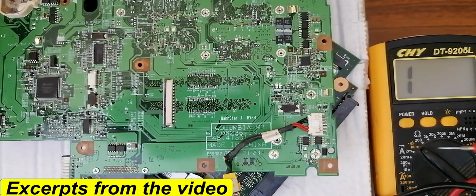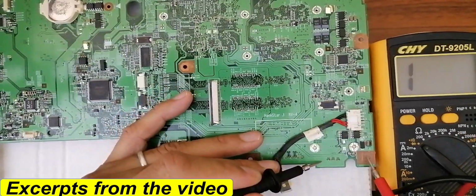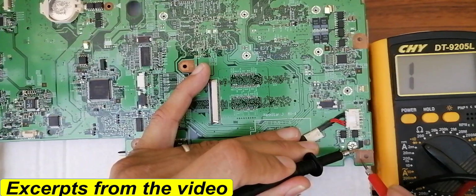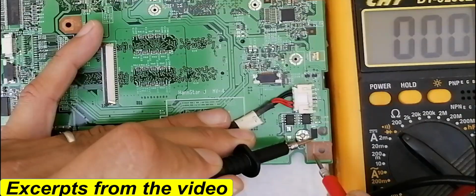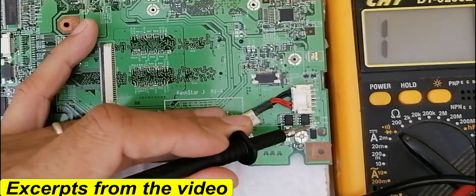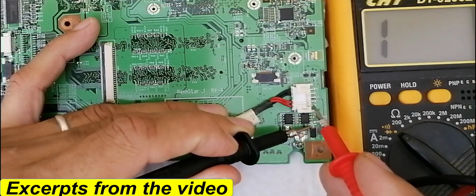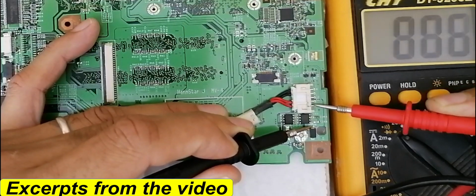We're going to select, of course, the continuity option in the multimeter because we're going to check the continuity. As I told you, this is the anode, so the anode should be connected to the ground. As you can see in the multimeter, we have a 0 reading and a beep, which means the anode is connected to the ground. But the cathode should be connected to the 90 volt power rail, to this red connector. So let's check.